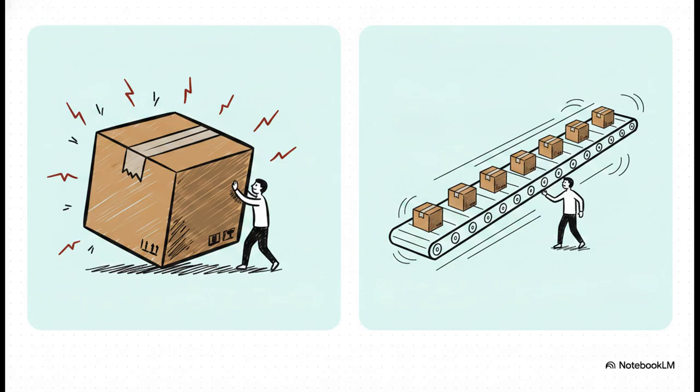It takes a lot of effort, it takes a lot of time, and you're probably going to struggle to get it done in one fluid motion. Well, RISC takes the exact opposite approach. A RISC computer might actually require more overall machine code to accomplish the exact same task, but instead of one massive box, it breaks the task down into many small, light boxes. The operations are so much simpler, which allows the processor to move them incredibly fast.